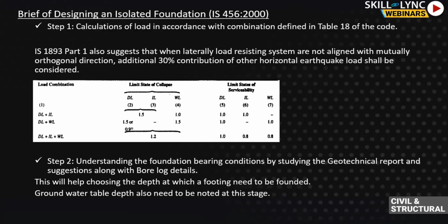Although one thing one might have to note is that the groundwater table depth is a critical point which would be provided in a geotechnical report, which one needs to take into account for reduction of soil density if the water table is such that during the rainy season it floods, or during the dry season it is not as deep as the depth of the foundation.